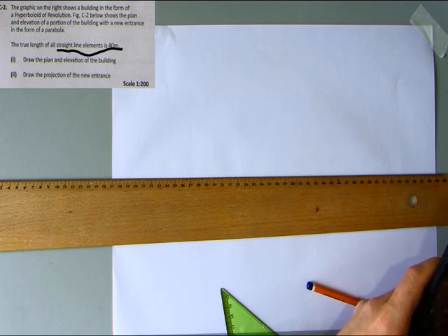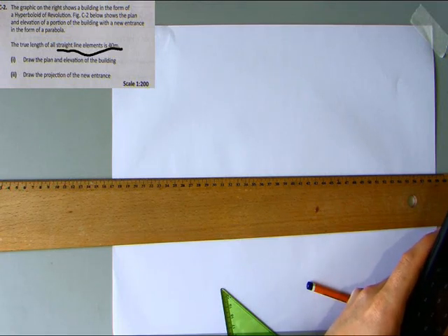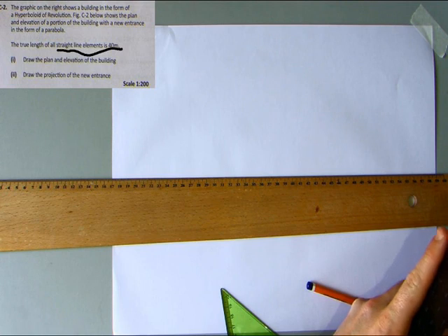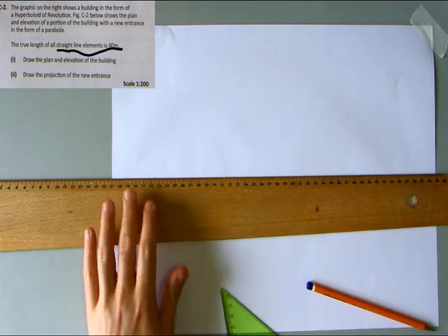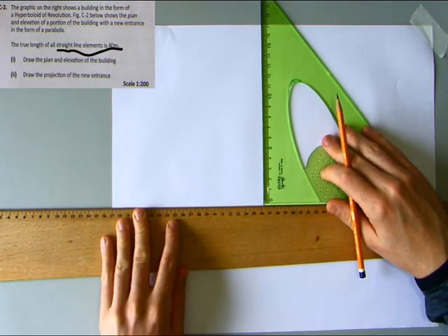We multiply that by 1,000. Why 1,000? Because you have 1,000 millimeters in a meter. And then you take that answer, which is 25,000 millimeters, and divide it by 200. And that's going to be your overall dimension of the height of your object. Okay, so 125.